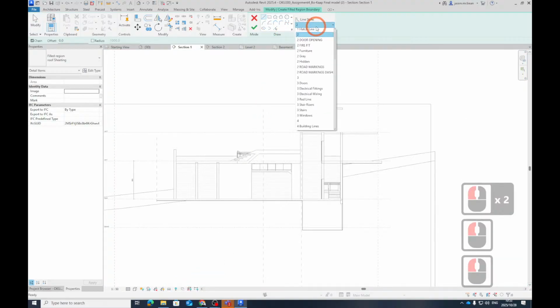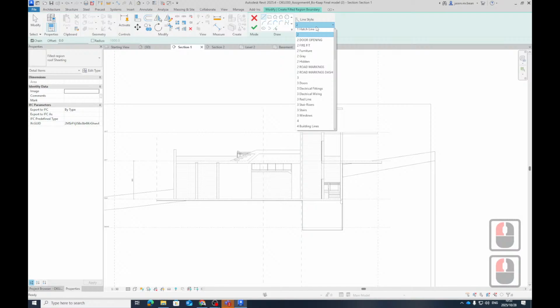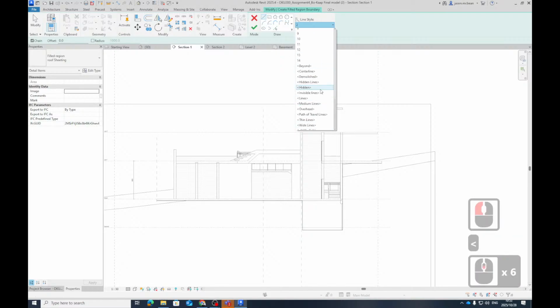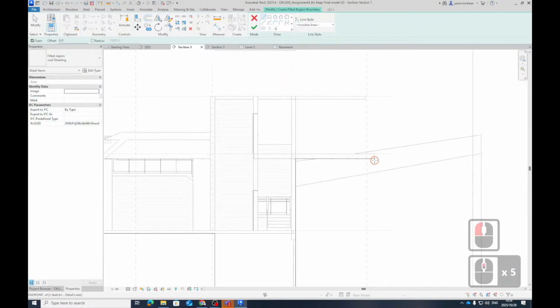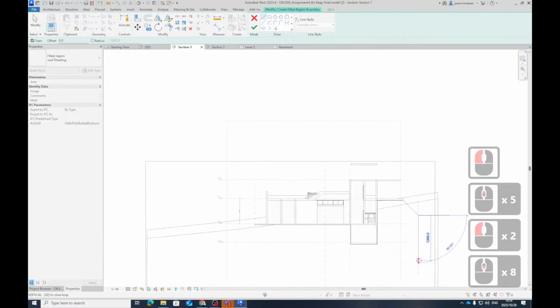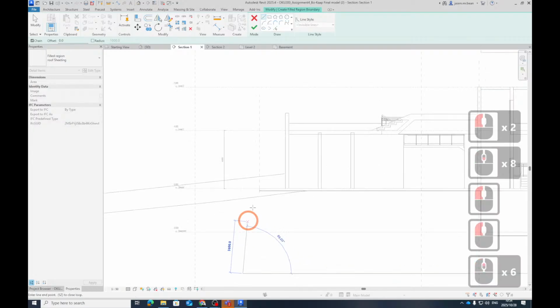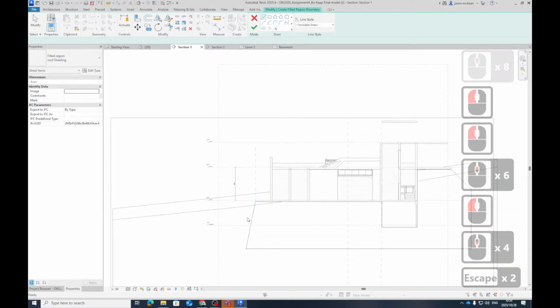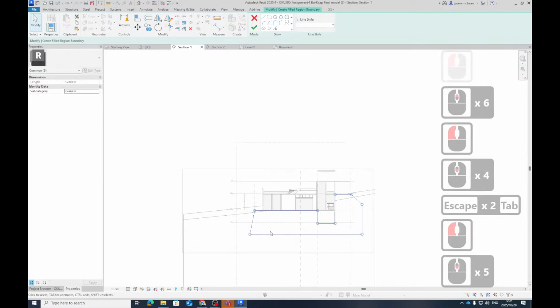This is very important. This needs to be an invisible line on your keyboard. You see that there? See what I've done? Shift and that key goes to this. These you can't delete. They're built into Revit always. Invisible line. So you just have to close a series of lines. You just got to close this, so make sure everything's closed. Tab once or twice. See those dots?